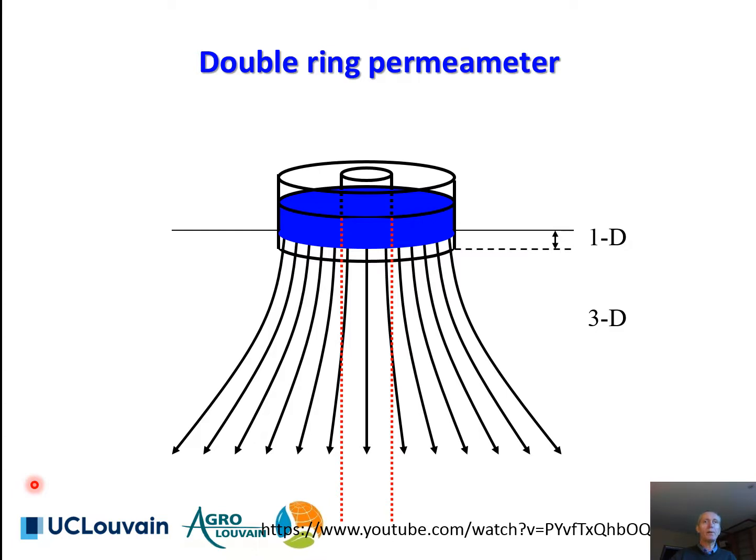The double ring infiltrometer forces water to infiltrate from two separated reservoirs at the soil surface. Yet the fact that the central reservoir sits inside the external reservoir implies that the flow below the central reservoir will mainly be vertical. The infiltration from the central reservoir in the double ring experiment therefore allows us to simulate in situ an experiment for which an analytical solution exists.